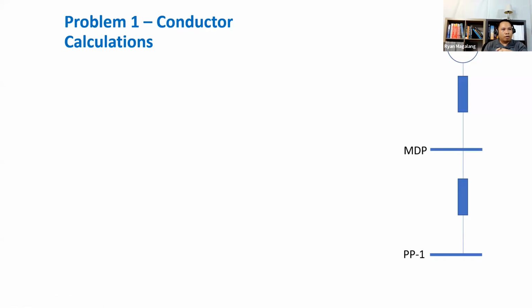So our short circuit amps is 45,000. And then let's assume the X/R value to be 12 because it's not given. Like I said, try to get that. So our V line to line is 480, which leaves us with V line to neutral equal to 277 volts.